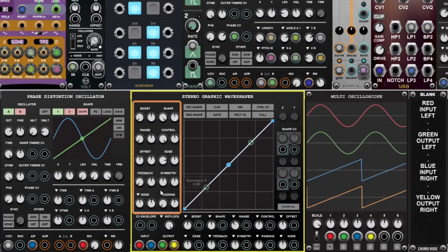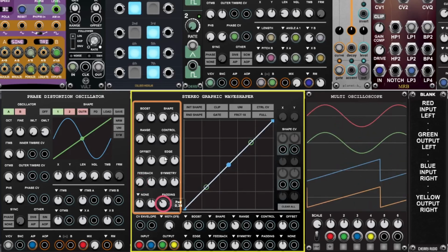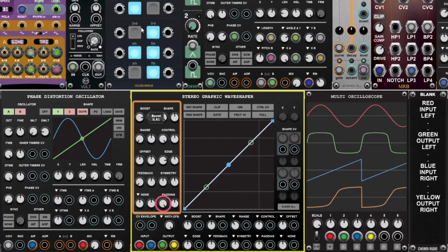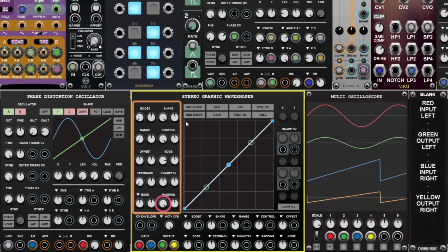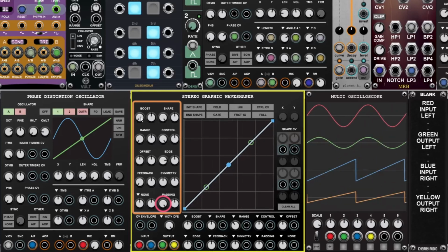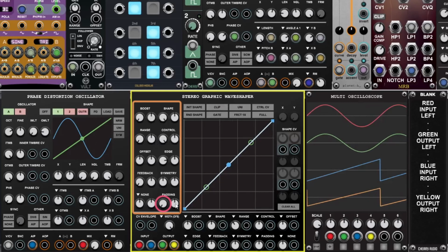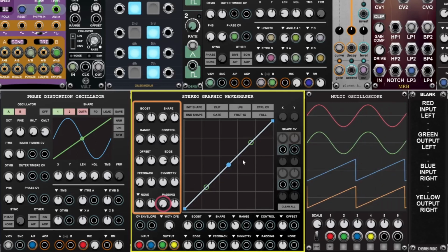And then there's the padding knob, which applies a logarithmic function to the input signal that is effective above 5 volts to smooth out clipping and folding behavior. This does also scale down the signal going into the waveshaper in order to accommodate for the onset of the logarithmic shaping. Padding can tame a very hot input signal and give a more rounded edge to the overshoots.